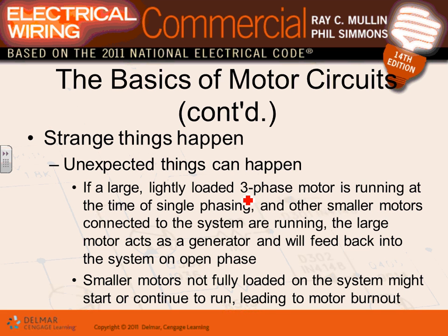you could lose a phase and you don't even know that you lost a phase if your system is lightly loaded. Be aware of this one, Derek, when you become a big engineer. You go there, you could be in a plant and you lost a phase and the equipment is still functioning for the most part appropriately if the equipment is lightly loaded. What's a lightly loaded, guys? I have a 10 horsepower motor and I'm only pulling 5 horsepower out of it.